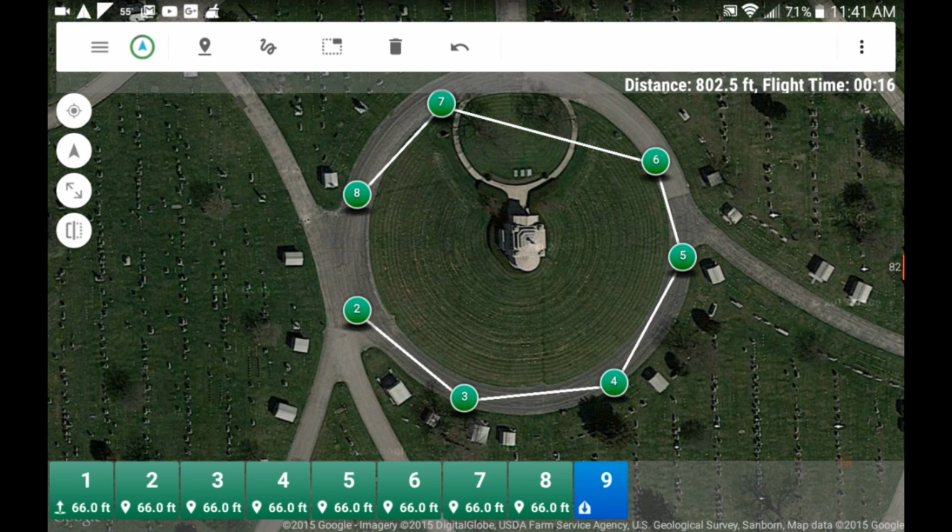Most important thing is flying where you have absolutely great satellite coverage, where your HDOP value is something like 1.5 or 1.7. Anything less than 2.0 will assure that Solo behaves and returns home pretty much right on the same spot it took off from. And Solo will always do that if you press the button on your controller for it to return home. So always know that option's available.